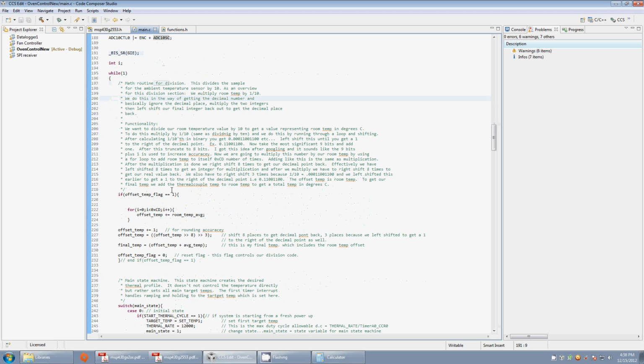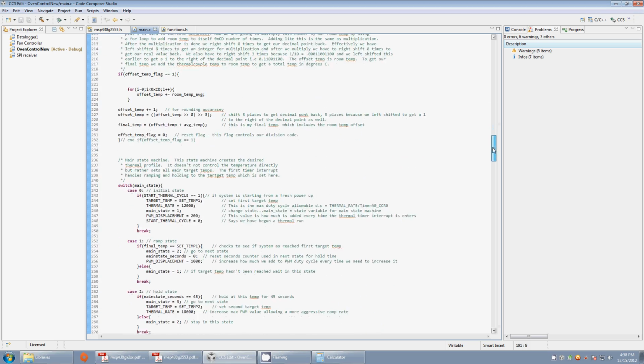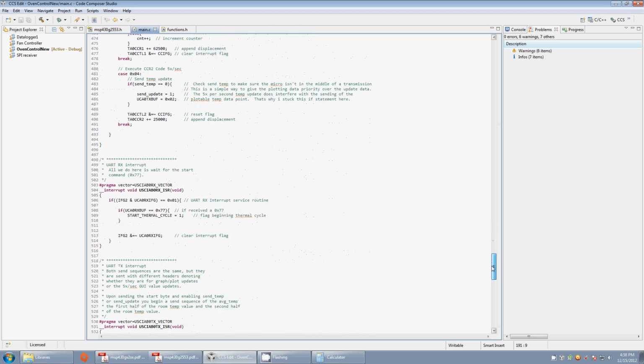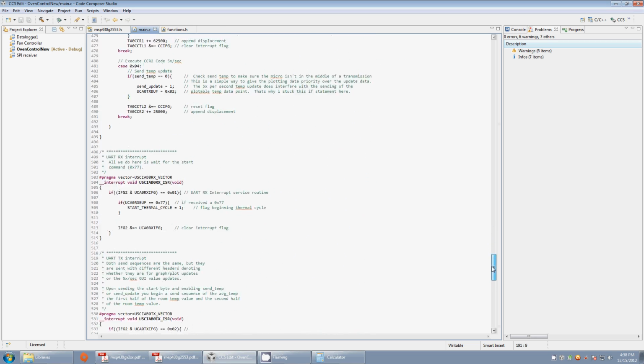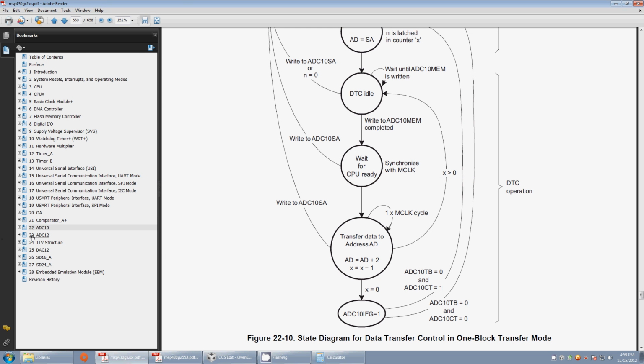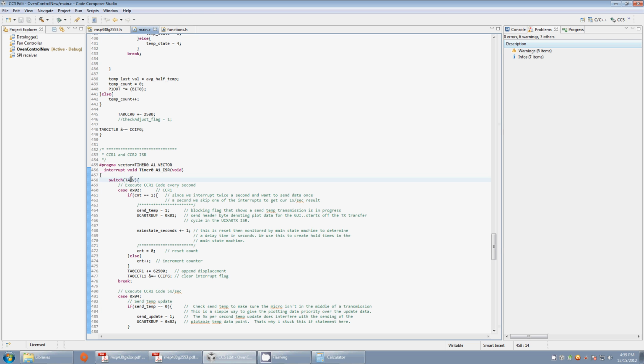So let's jump down to some simple interrupts real quick, so this video is not too long, and then we'll make a second part to discuss some more complicated ones. The first one is the interrupt for timer A0, as we mentioned above, and it's going to be for capture compare 1 and 2. If you look at that, you've got a timer A interrupt vector table, and so that's pretty handy. What you can do is a switch statement to switch on that, and then just make a case for each capture compare register.